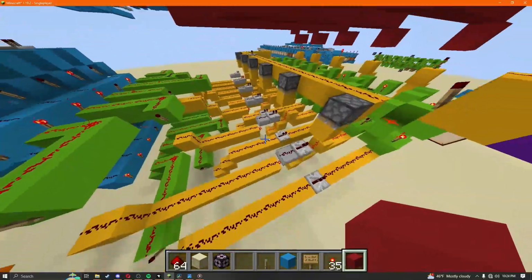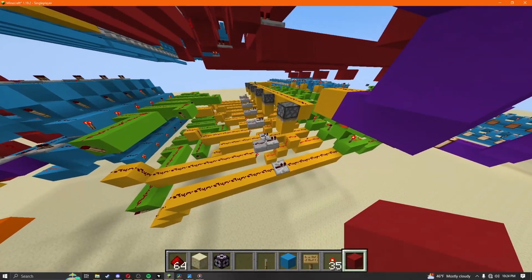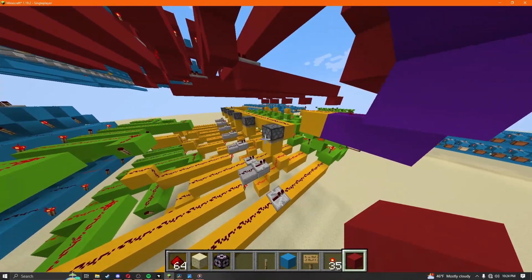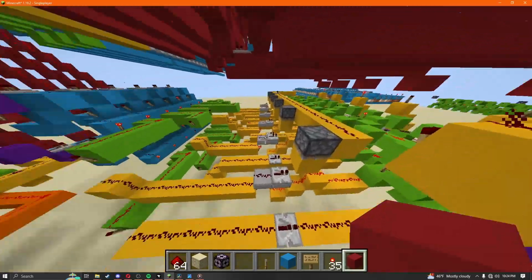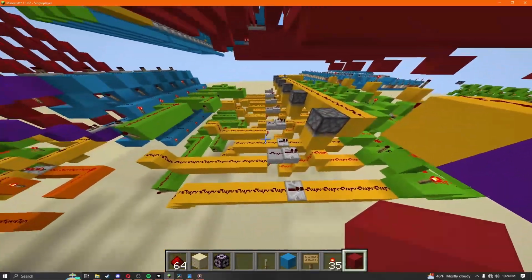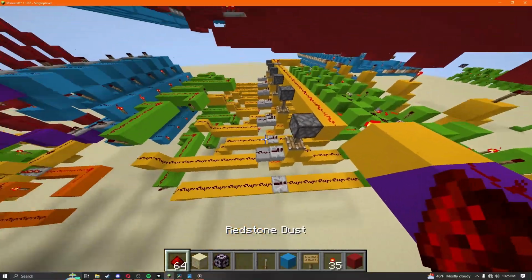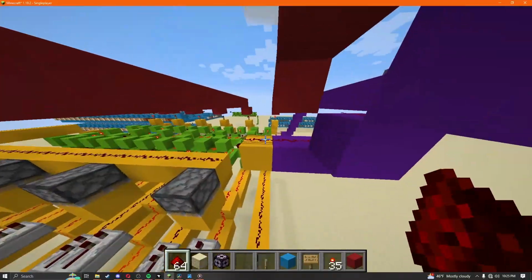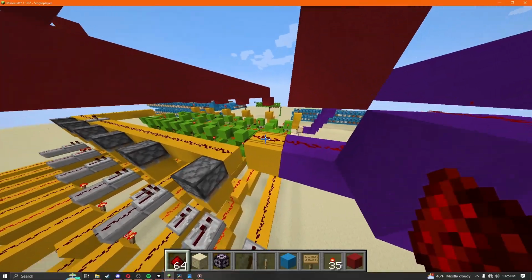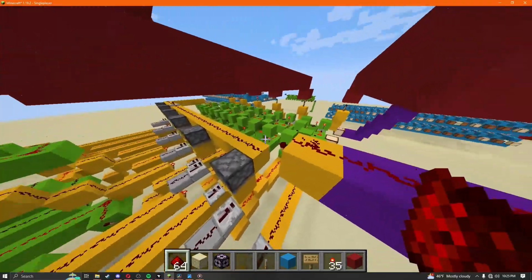The way we do a subtract instruction, if you remember in binary, we can represent a negative number by flipping all the bits and adding 1. Same thing here. So right now the subtract instruction is currently set. What that looks like is doing this. So right now we're adding. Now this wire determines what mode we're in.